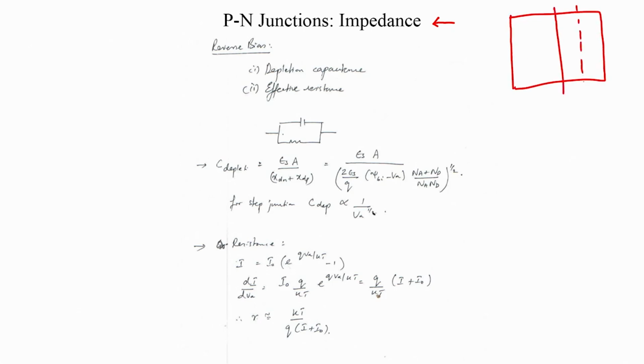you had a depletion region, we derived electrostatics for it, and we found that when you apply a forward bias, we had excess holes being injected in the N type and excess electrons being injected into the P type, and those excess holes would recombine and therefore you had a concentration gradient, and likewise with the injected electrons.